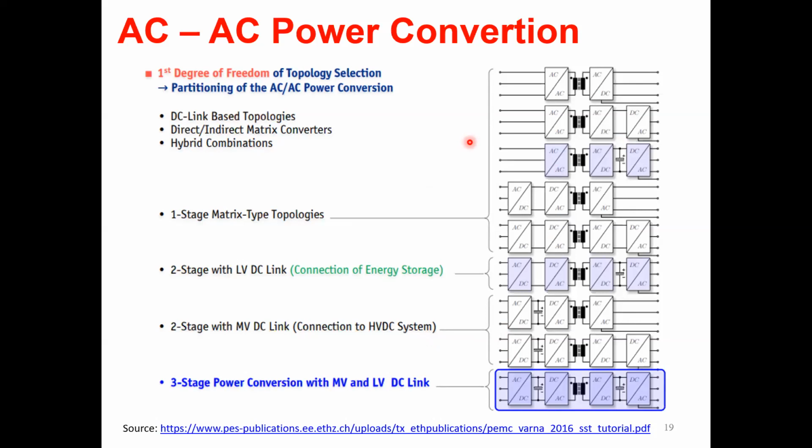So what are all the primary aspects of it, right? One is basically as we discussed before. If we have a pulsating DC bus on our intermediate DC bus, like a full wave rectifier, that doesn't need an energy storage. But some applications have been using a stiff DC bus and still calling it a solid state transformer application. Some people dispute that it's more like a DC-DC converter, but some people say that we are anyway replacing a line frequency transformer with a solid state transformer. I don't have a certain opinion on that, but here I'm listing all the options which people are evaluating.